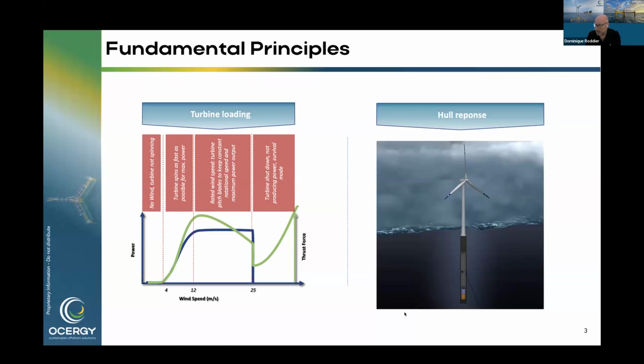And then when you stop, all of a sudden, you don't generate that lift. Your thrust force decreases tremendously, and then it's only a drag system. So the more wind, the more forces. In some cases, the 50-year storm, the design right here, can be lower or higher than this point. So you have to decide for both. If you look, in latitudes that are pretty far north and have very big storms, this is one of your driving cases. For the first project we did in Portugal, this was the driving case because the maximum wind wasn't that big.